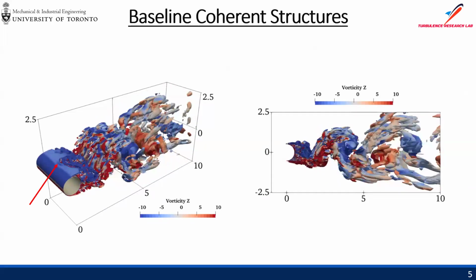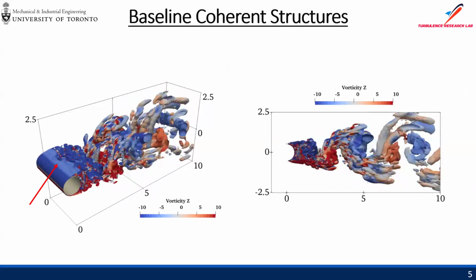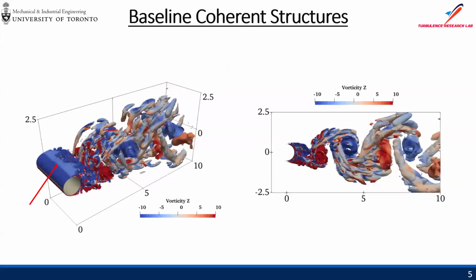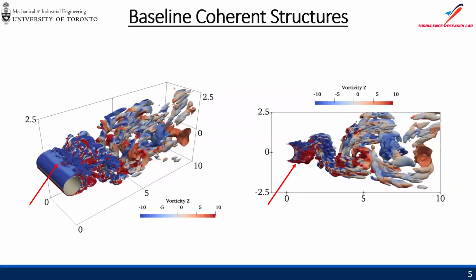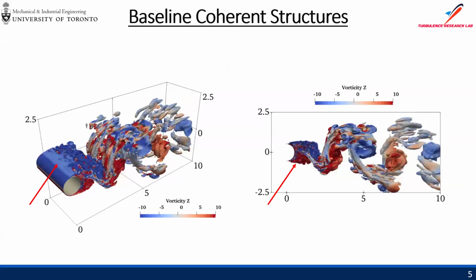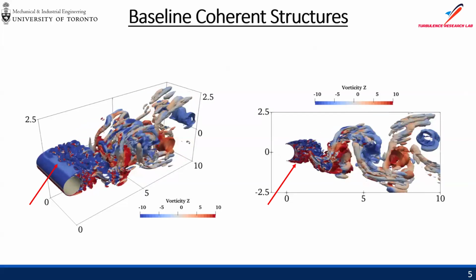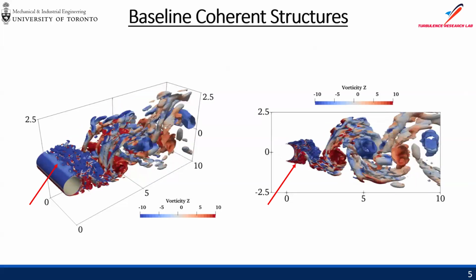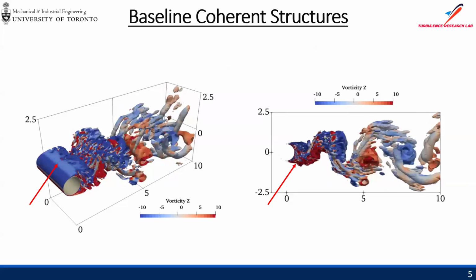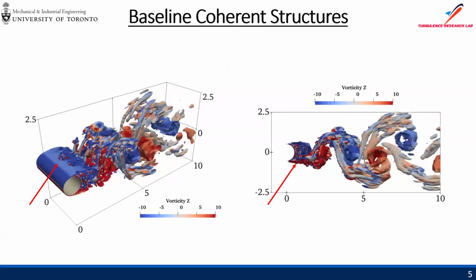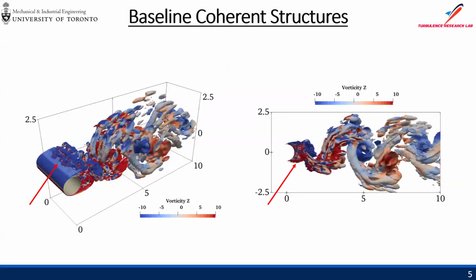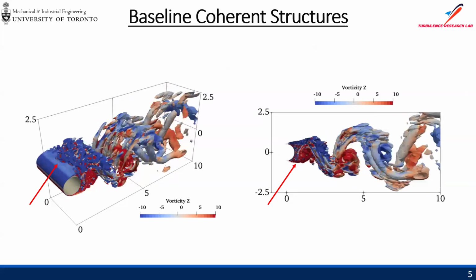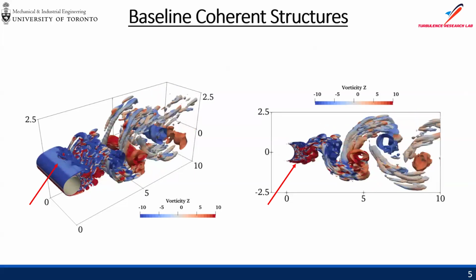There's quite a lot of streamwise and spanwise fluctuation, and the flow is overall quite turbulent. On the side, however, even though the flow is turbulent, you can still see a periodic flapping motion. This is actually the wake, otherwise known as von Karman shedding. This is the same or pretty similar physics to what you see in the wake of an airfoil on an airplane. Another thing that we can also see is the Kelvin-Helmholtz instability, basically the shear layer breakup.